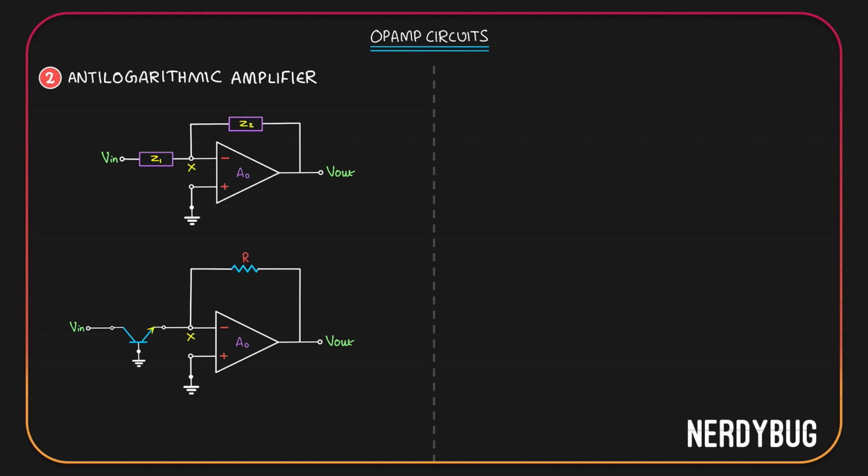What if I connect the emitter over here and collector over here so that collector will be at Vx, which is 0? Let us try that. Now collector is at 0 potential, base is also at 0 potential, transistor is diode connected, it will always be in active mode, but current will not be able to flow in this direction. We started assuming V in is positive. Vx obviously is 0. Current has to flow in this direction, but this transistor will not allow that.